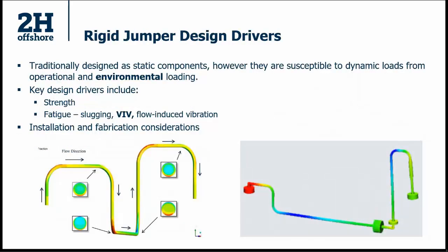Traditionally, however, these jumpers were designed mainly for static loads. And by static loads, what I mean is these different movements and also to just support their own weight and the loads that go into the connectors. But over the period during operations, we've seen that the jumpers see a lot of dynamic loading, and hence there are a few different design drivers that go into the design of a jumper.